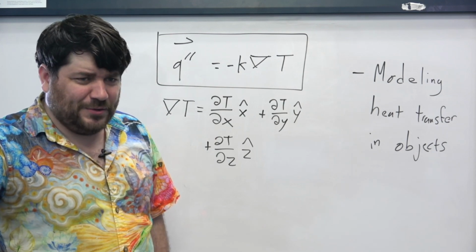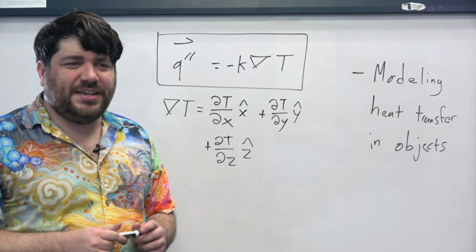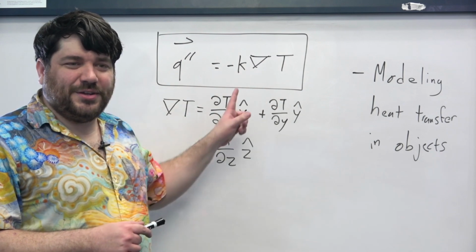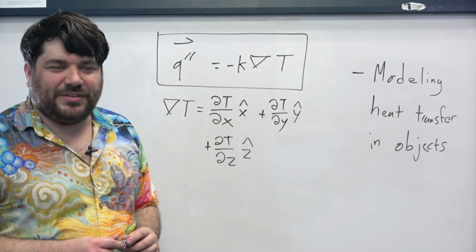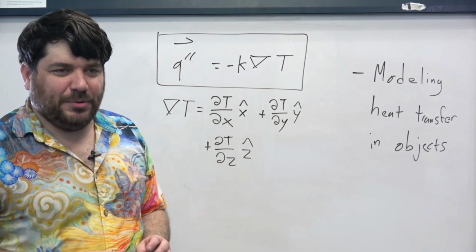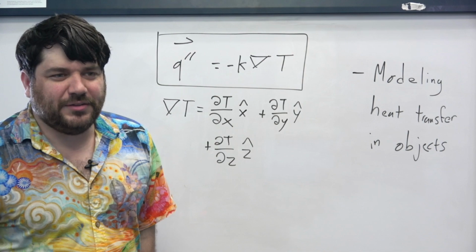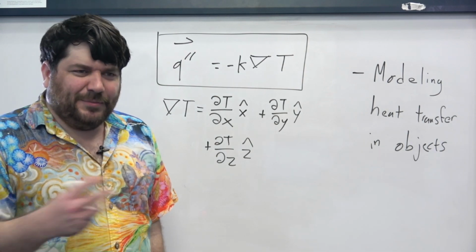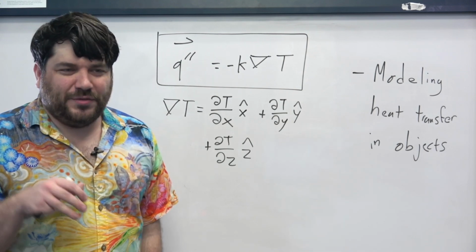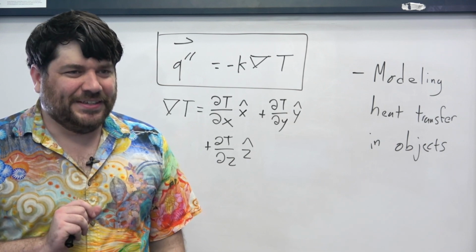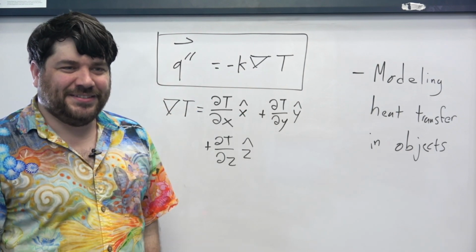And if I consider a temperature gradient, and I just make the same assumptions that I did when I was trying to derive the H times delta T equation, I just wind up getting this linear equation that relates delta T to Q double prime by some just linear constant fudge factor K that we pull from experiments, all right? And that negative is just there to accommodate the fact that this is a vector equation. So once again, we haven't uncovered any new physics, okay? This is just a mathematical model where we've tried to create the simplest equation possible and then just jammed all of the stuff that we don't know or like into the K, all right?